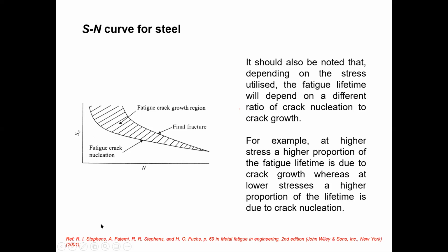Say I select one single stress, assume a horizontal line, somewhere here. With the lower boundary, this material will fail at this number of cycles, and with the upper boundary at this one.